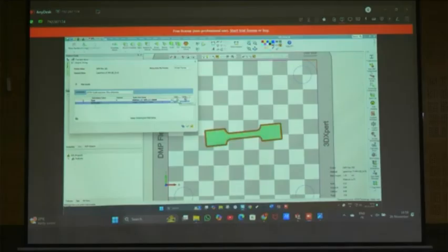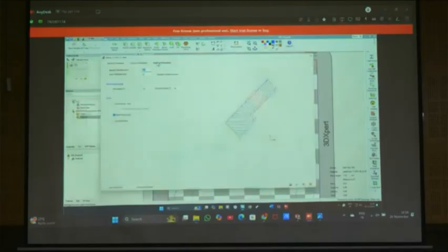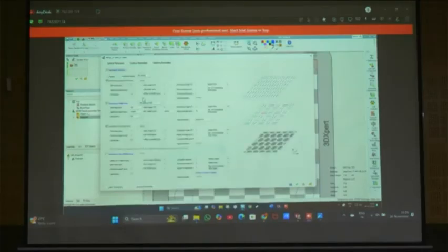You can see here, settings. General parameters means layer thickness, we can see here layer thickness, 30 microns we are keeping, and we can calculate the number of slices, 367 I am getting. And hatching parameters, the main thing will come here. Hatching parameters means scanning related parameters, like scan speed, laser parameters, and hatching related means hatch distance and the scan pattern, these things we can change, okay.